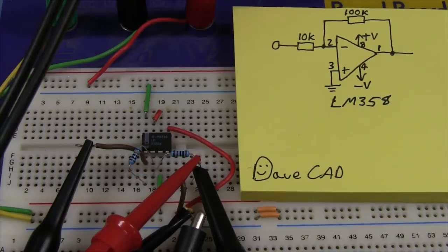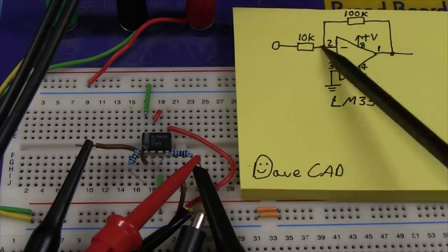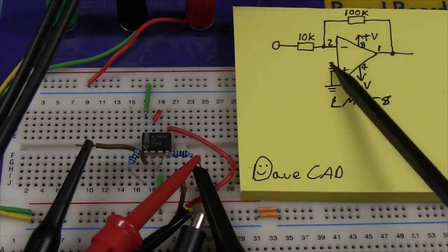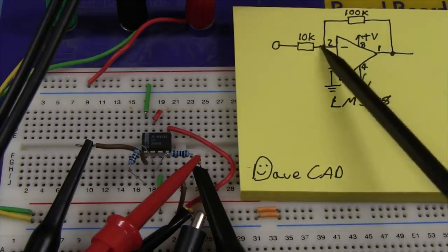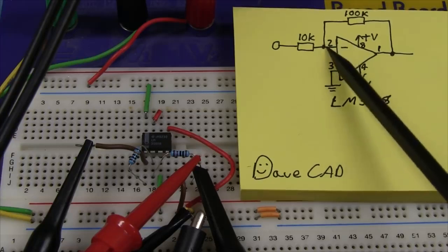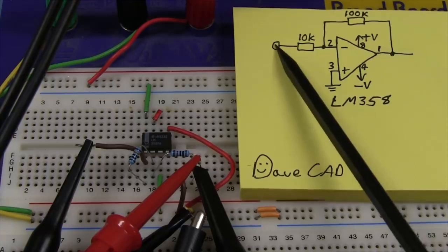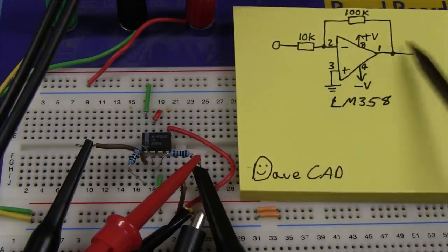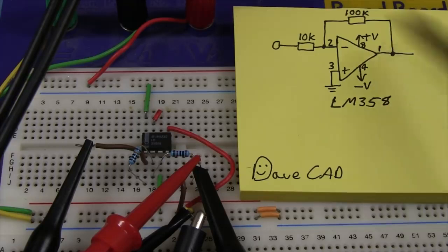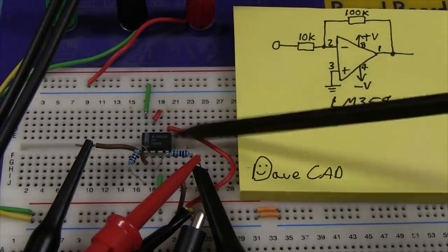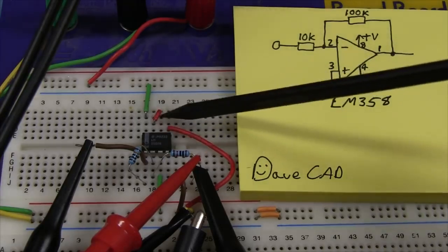Alright, we're at the breadboard. Let's take a look at an inverting amplifier here, because I wanted to show you that virtual ground point there, just to show you that there really is no signal there. It actually vanishes, in quote marks, when you go from the input here to here, and then it magically reappears at the output, because that's how an op-amp works, as I've explained. Anyway, got a jellybean LM358 here. It's actually a dual op-amp, so we've just terminated the top op-amp here.